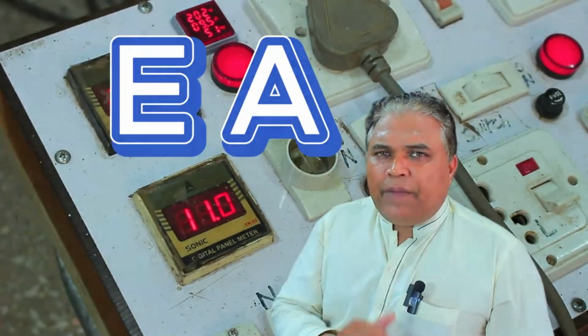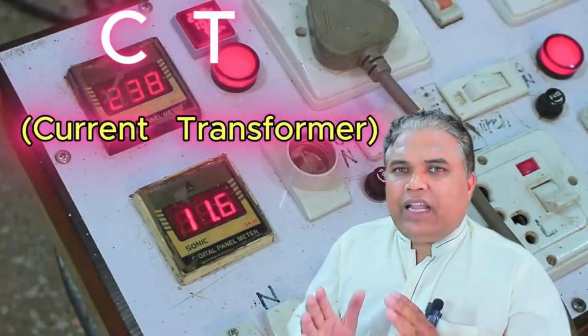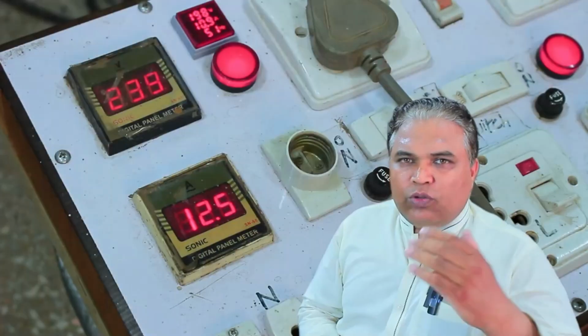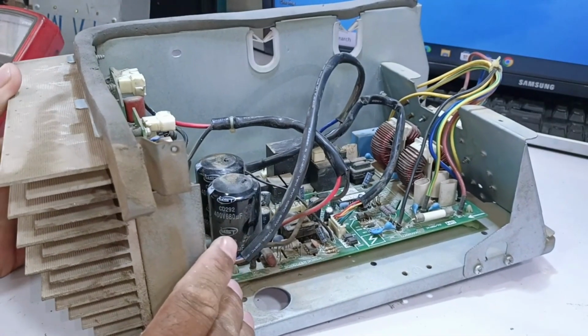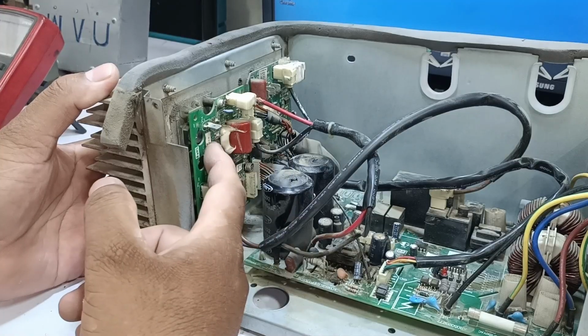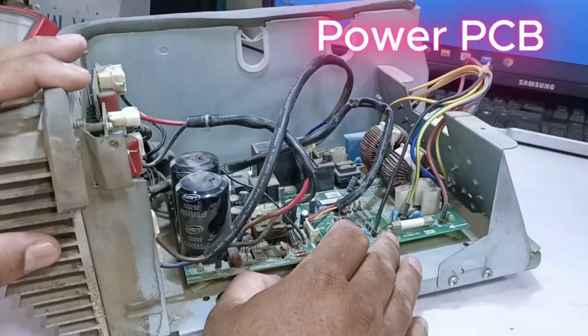The manufacturer says that the EA error is related to the CT, or current transformer, so there could be an issue with the current detection circuit as well. Let me explain where the current detection happens. This entire motherboard contains not just one PCB, but 3 PCBs. This one is the power board, the left side has the PFC board, and the right side has the IPM PCB. The fault is in the power PCB.